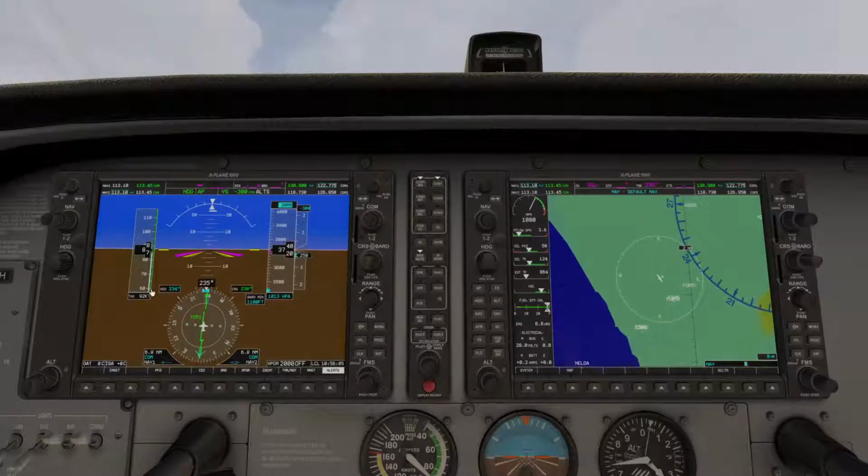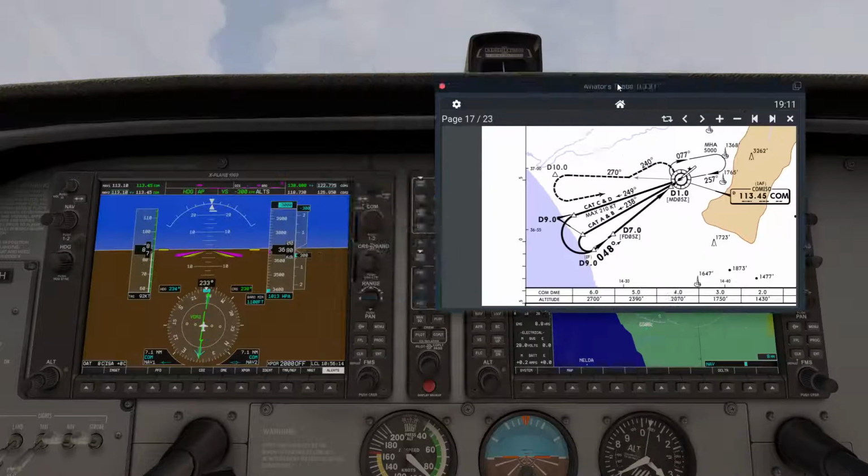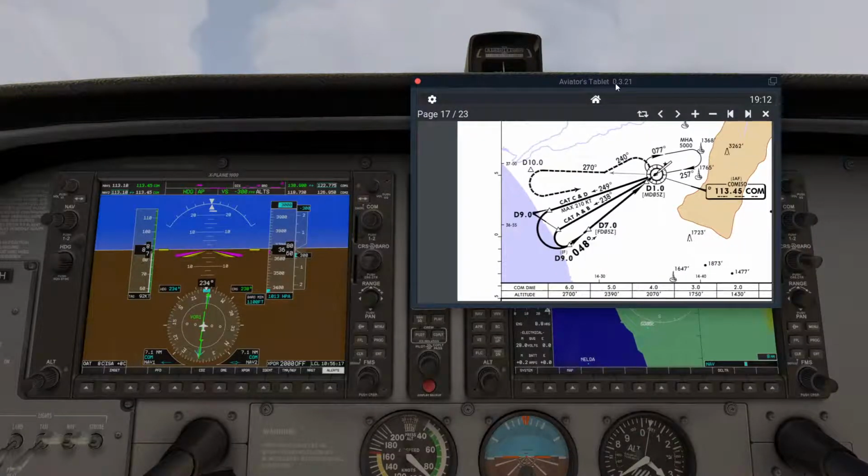Two degrees again to the left for the correction. The CDI, 7 miles out and 2 miles remaining to the 9 miles out of the VOR on course 238. The CDI is getting center, heading 236 is good. Almost 600 feet to reach 3000 feet.